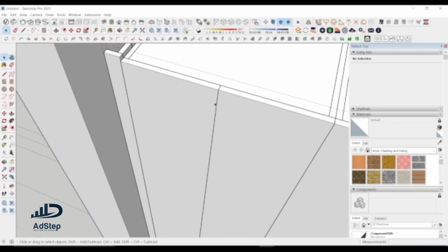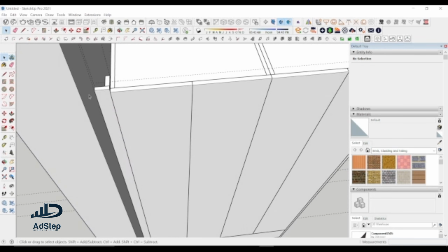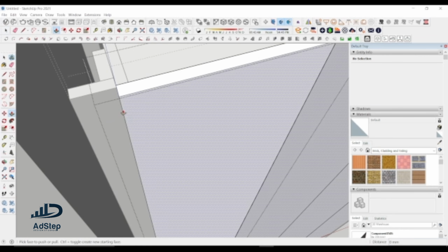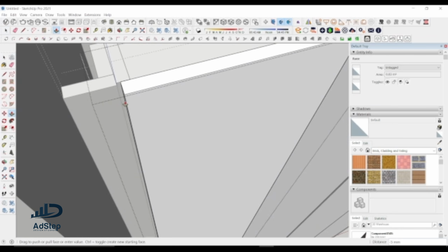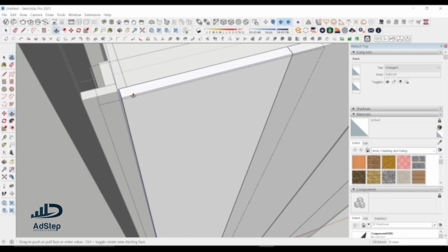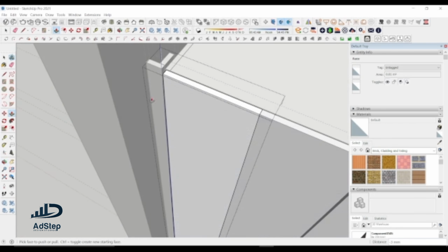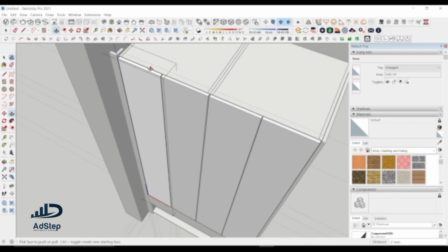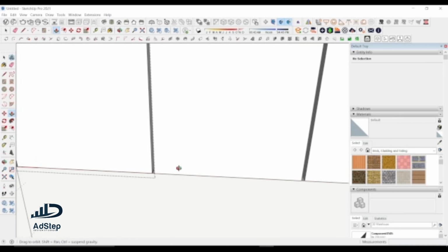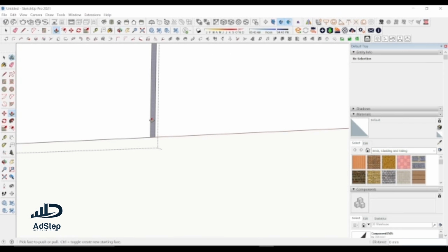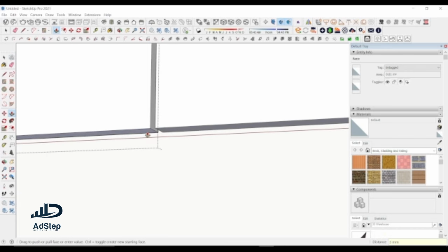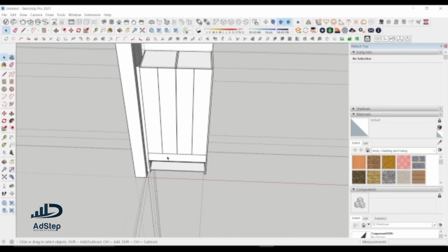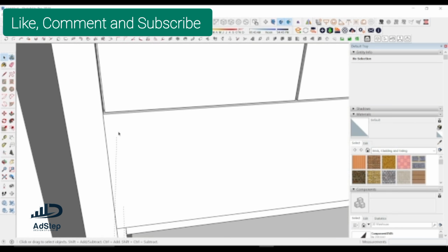Because of edge tape and spacing, so that the door will open freely, I need to give the door some spacing. So let me give the door some spacing. Here 3 mm, up 3 mm, here 2 mm. Anything I do is going to affect the other door. Here 3 mm. So I've given some spacing. So the openings, there will be spacing. So the draft is true.